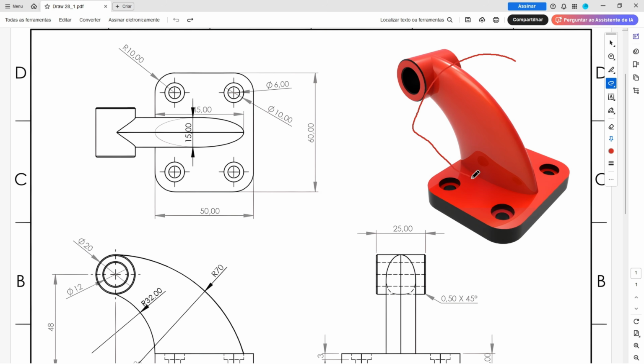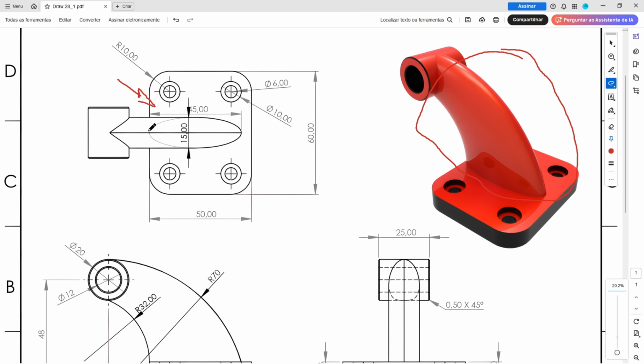Now we will create the main body here. To create this, we use the surface because the loft won't work here. And we will select the top face and make this sketch. We will create this ellipse here in the top face. But this ellipse must be divided by 4 arcs, okay?